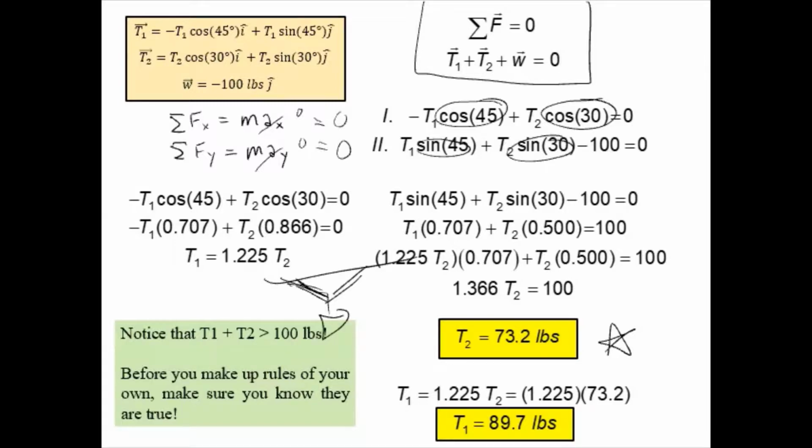So when we tie things on, hang things like this, it's really important we understand the physics of this, and we can solve out our engineering equations to get the right tensions in these things. Because if we buy the wrong strength cord, obviously if that speaker falls, it could kill someone. And so typically in engineering, you have what we call safety factors. So looking at this, I would say, well, gee, 100-pound cable would probably be okay, because neither of these tensions are going to be bigger than 100 pounds. But usually what we do is add in safety factors. So I probably wouldn't recommend a 100-pound cable. I would say probably use 200 or 300-pound cable.